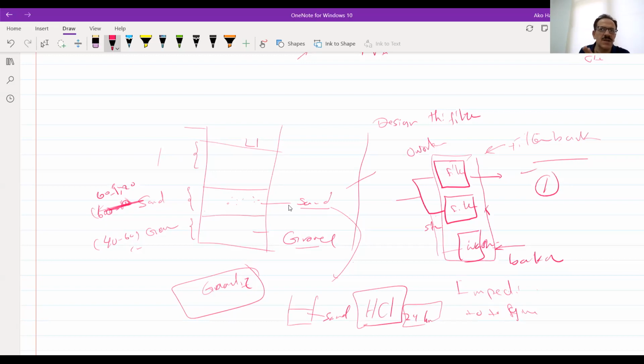If there is any loss in weight, it means this sand is not clean. It has organic content in it. Now, this sand will not be allowed to be used. Usually the quartz one that is free from organic material should be used here.